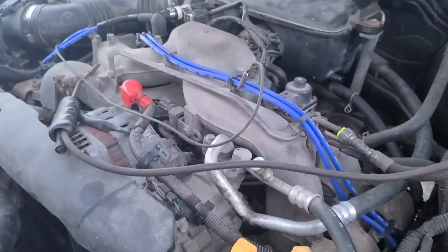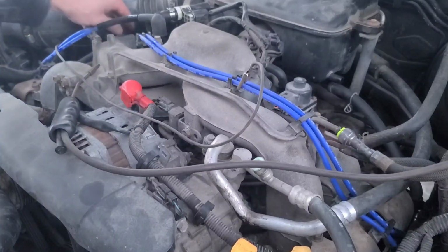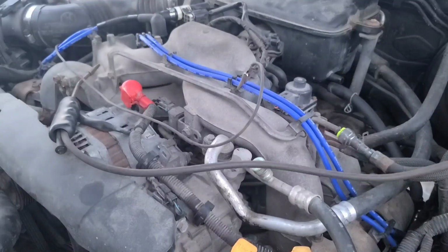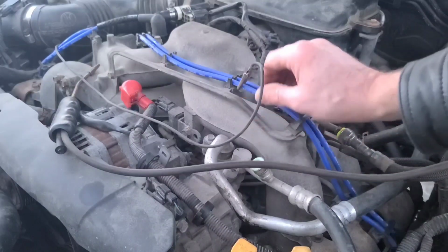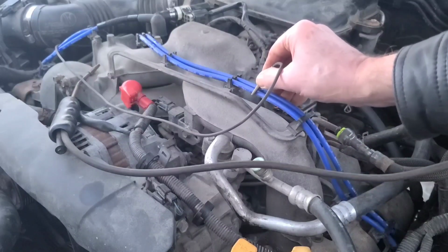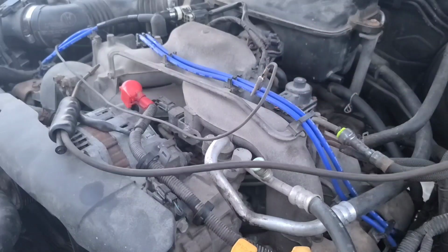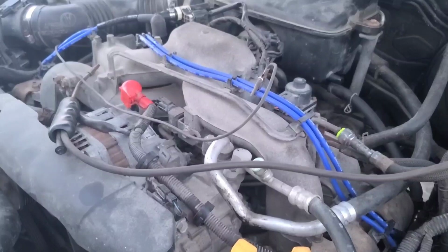So I got a spark plug wire or a jumper wire connected to one of the coils. The other spark plug wire is still attached to the companion cylinder, and I've got about a 1/2 inch air gap set there. We're going to see if we got spark. I didn't hear any spark. You're going to have to watch this video and see if we have spark.